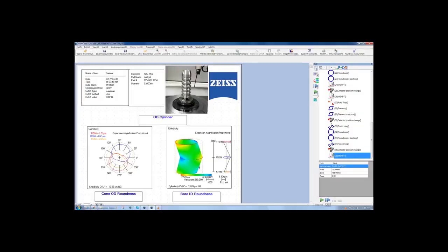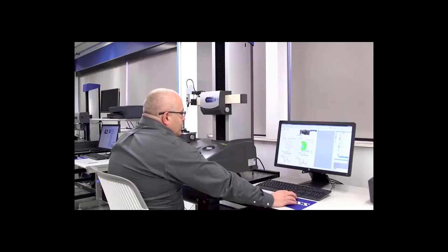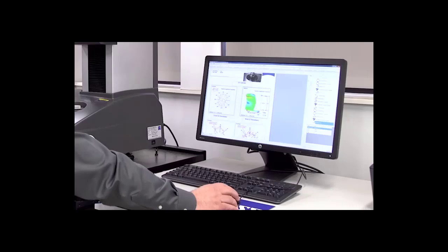You can put your company logo, your measurement information, date, time, what type of measurement cutoffs, whatever you want to use. The information that we had the operator input at the beginning of the program appears here. If we look at some of the measurements that we have performed today, we have our outer diameter cylindricity. We show it here in a 2D plane, also in a 3D plane. We can also at any time adjust this 3D plane to see the optimal view from a three-dimensional standpoint.